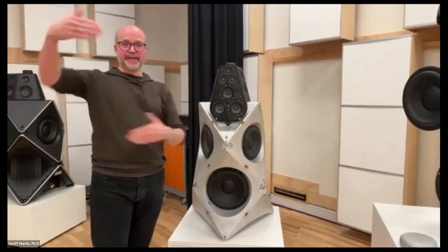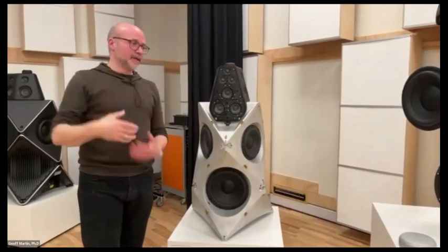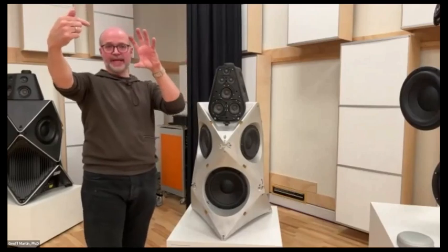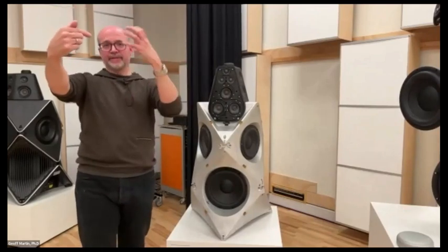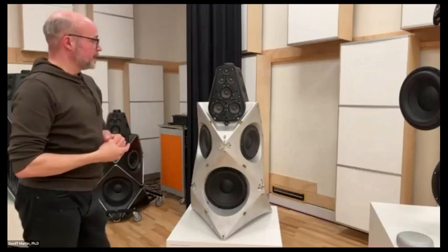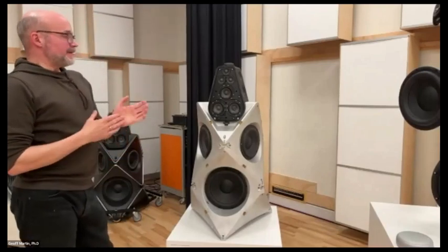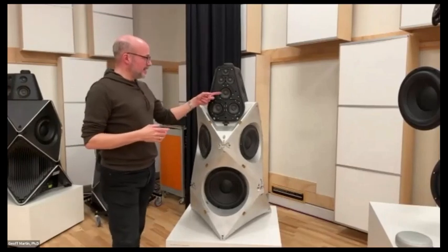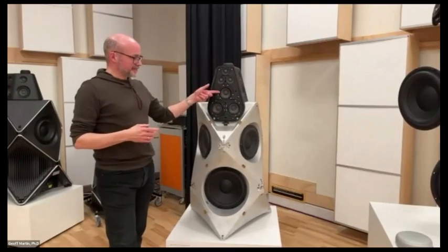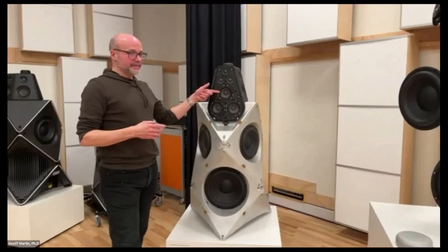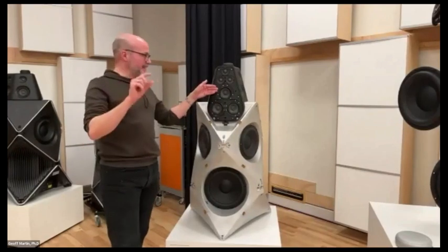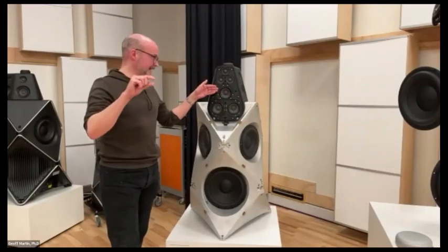That's a 12 meter by 12 meter by 12 meter room, where there's a microphone sitting out in the middle of the room, and this thing goes out on a crane, and we measure it, rotate, measure, and so on and so on. And we found a problem with this prototype. The problem was that on axis, our main mid-range driver wasn't giving us a flat magnitude response like we expected, we had a dip at about 800 hertz by about a dB.